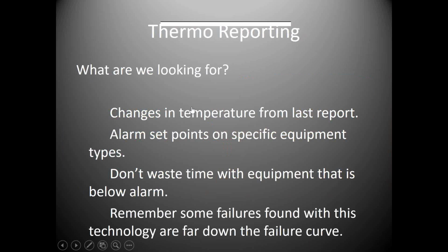So when you're using thermographics, what are we looking for? We're looking for changes in temperature from the last report. A lot of times we'll go out and do a scan, take some specific pictures, see what the temperature is, and then what are they next month and what are they the week after. So now we can track data. We want to set some alarm set points on specific equipment types.